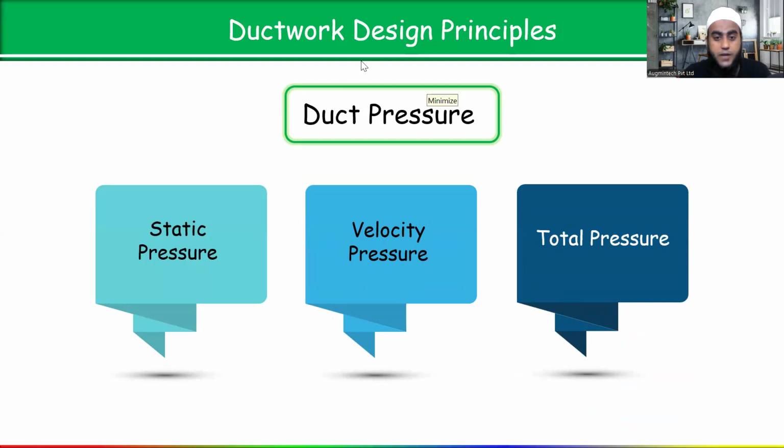Don't worry, someone is asking me how much clearance should be between the beam bottom and duct. So remember, the minimum clearance is 100 mm after placement of insulation and everything. You have to maintain a minimum 100 mm gap from the false ceiling and also from the slab. And if any beam is coming, we have to maintain a minimum 100 mm gap after the placement of insulation.